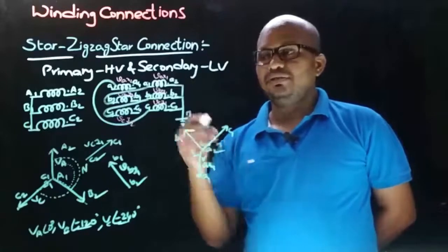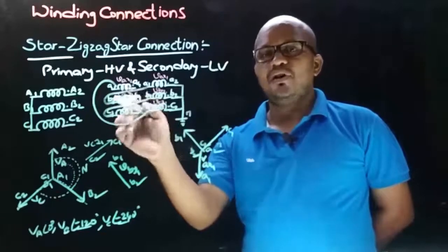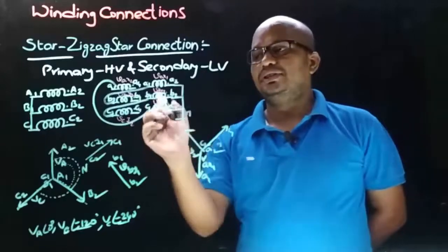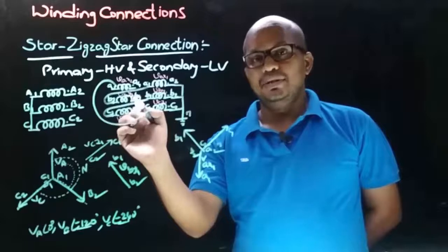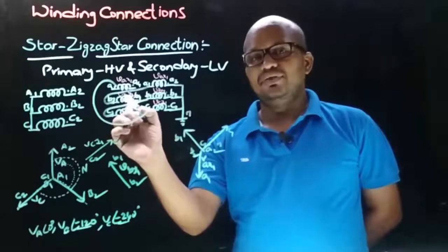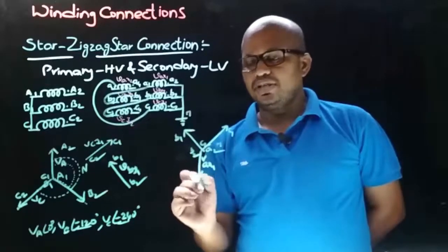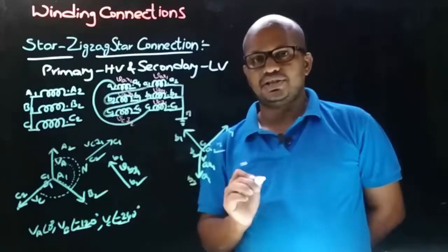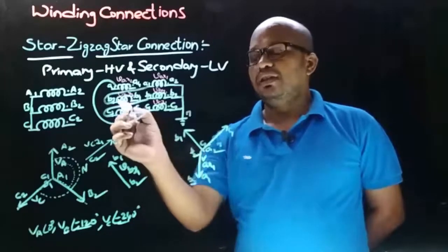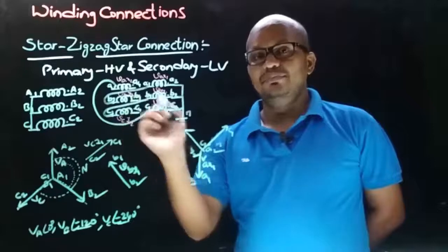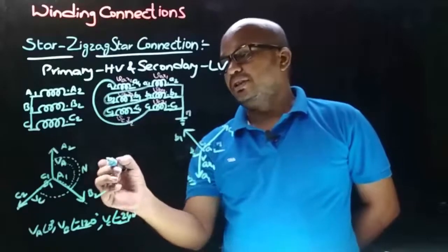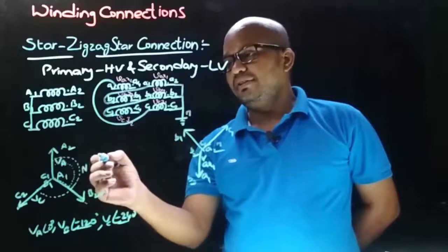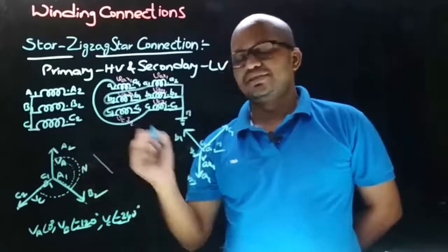Now we need to draw the phasor diagram for this other half section of LV winding. And observe that here to A1 there is B3 connection. Means we must draw the VBY2 phasor from A1 because A1 is having B3 connection. Therefore let's draw the secondary side VBY2 phasor, parallel to primary side VB phasor somewhere here like this.